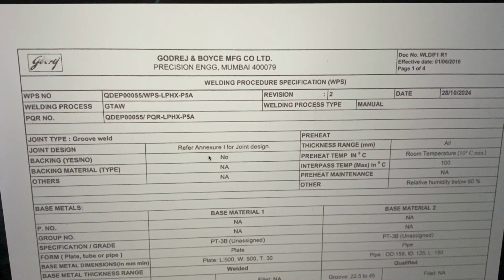Then on the right hand side, here we have whether we are going to have a preheat. Are we going to heat the joint by a different method, electrical method, a gas burner or infrared, and to what thickness and to what temperature are we going to do the heating? Generally up to 25 millimeters, no preheat is recommended for carbon steel, but if it is aluminum, even for 6 to 8 millimeter, you will require a preheat because of its high conductivity. So depending upon the material and the thickness, you will select a preheat.